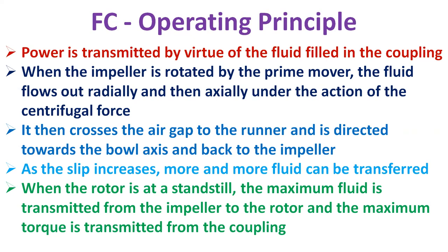Slip is an important and inherent characteristic of a fluid coupling, resulting in several desired advantages. As the slip increases, more and more fluid can be transferred. When the rotor is at standstill, the maximum fluid is transmitted from the impeller to the rotor, and the maximum torque is transmitted from the coupling. At this maximum limiting torque, the fluid coupling also acts as a torque limiter.